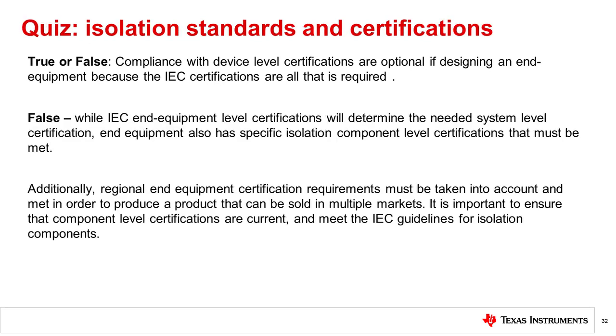False. While IEC and equipment level certifications will determine the needed system level certification, end equipments also have specific isolation component level certifications that must be met. Additionally, regional and equipment certification requirements must be taken into account and met in order to produce a product that can be sold into multiple markets. It's important to ensure that component level safety certifications are current and meet the IEC guidelines for isolation components.